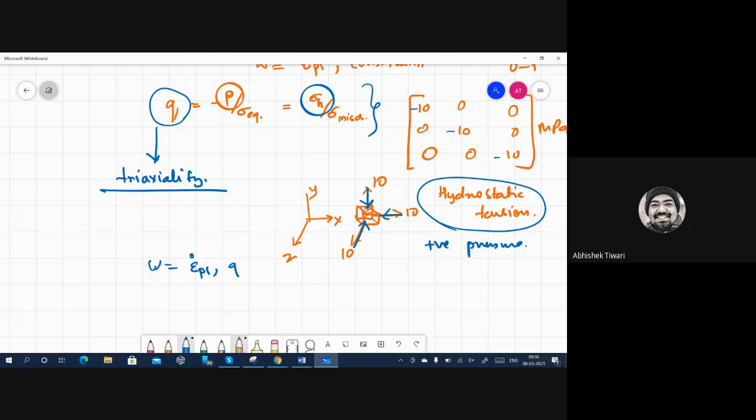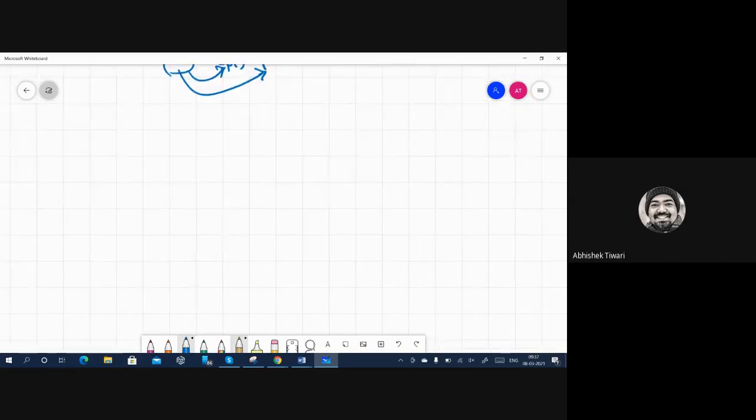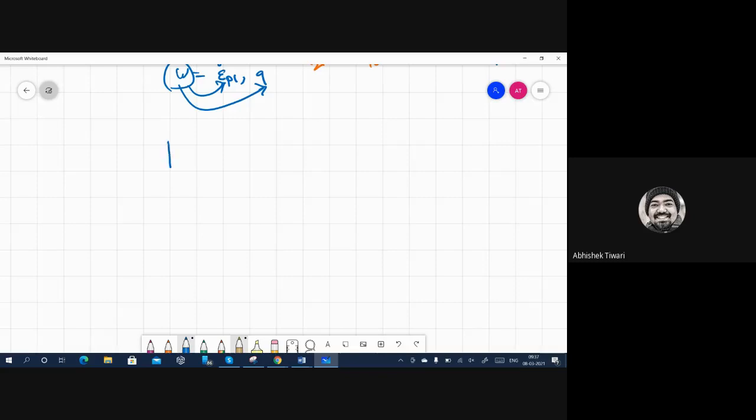So if we have to define damage, how do we get these variations? So what is the relation of the damage parameter with this and with this? In order to get it experimentally, different experiments are usually performed. So you take a tensile specimen which has a notch in it, and you make different notches with different root radii, and each root radius would represent a different level of constraint.